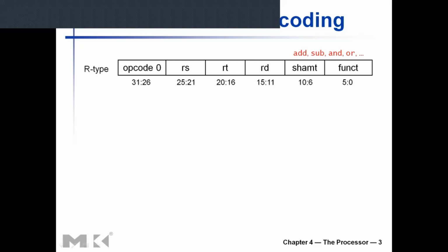A register is 32 bits wide, but how many registers are in the register file? 31, as in 31 are accessible, free to use, but the 32nd register rather, as we start from 0, the 32nd register is the link register. So we have 32 total in the register file.